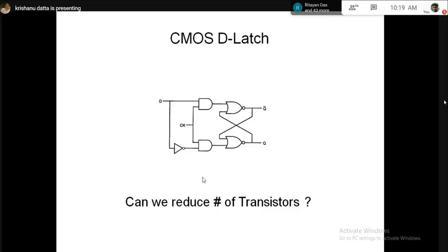Now, if we implement a 22-transistor based latch, then the number of transistors will be too much, because there are millions of latches in a high-end processor, right? If each latch itself takes 22 transistors, then how can we cope with the demand for transistors? That will be too much. It will cost too much power, area, timing, whatnot. It has a big impact on the circuit. So technology started thinking about how to reduce the number of transistors drastically, while still functioning like our traditional data latch.